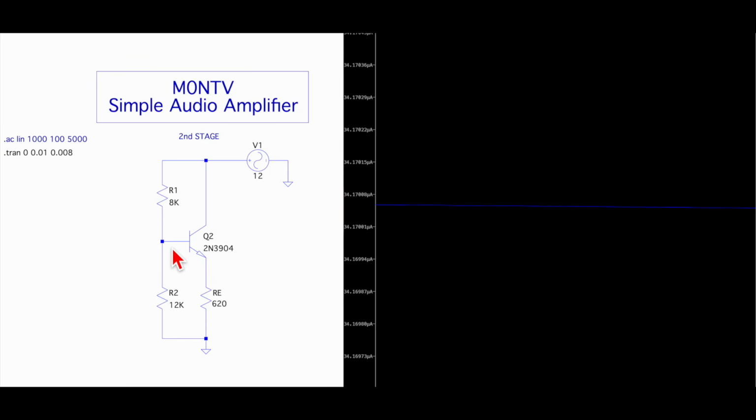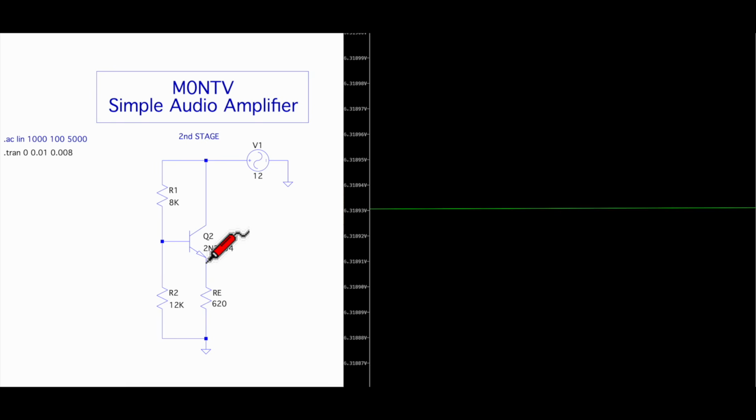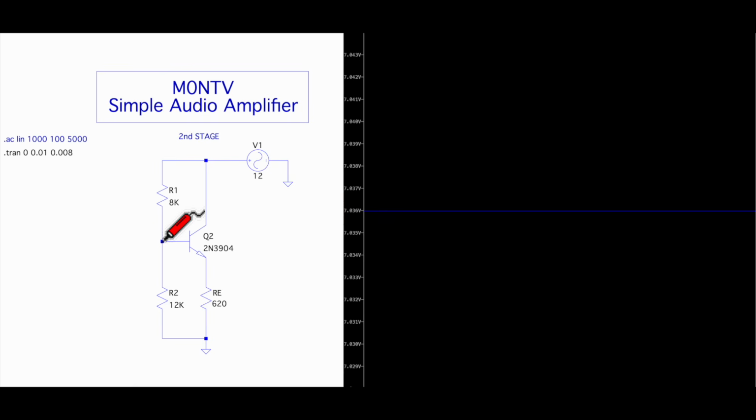And for the voltage divider, it's exactly the same kind of process, except now it's a higher voltage, because we haven't got 1.2 volts here, we've got 6 volts here. Now in our case, it's 6.3 it comes out to. So adding in the diode drop as usual, if it's 6.3 there, it's going to be about 7 here, which it is. And that's what we want to see.